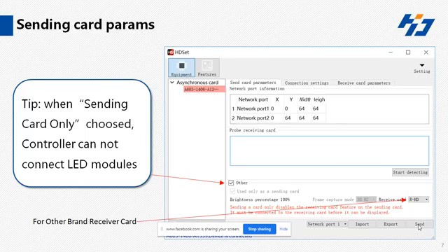Sometimes you face a problem, like you have connected a C35C controller or C15C controller with several receiving cards, but after doing the smart setting, the screen is not being displayed. Basically, the problem is there is an option you can see here, marked by a tick, other, and in that option it says use only as send card.